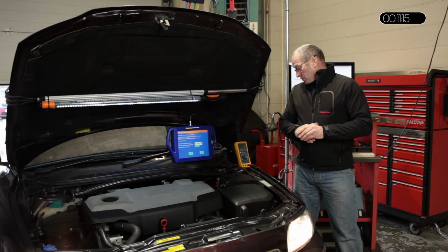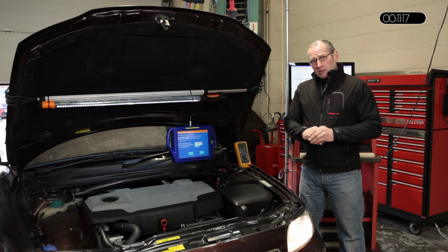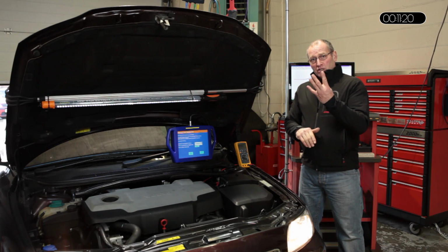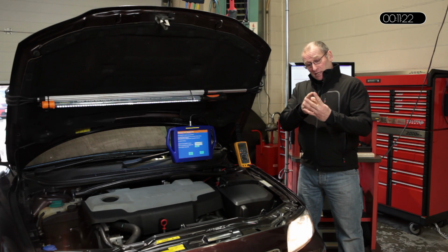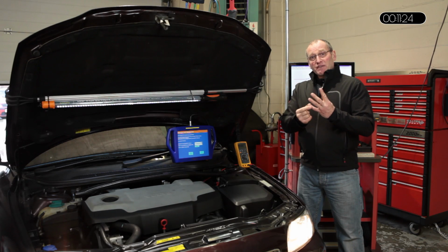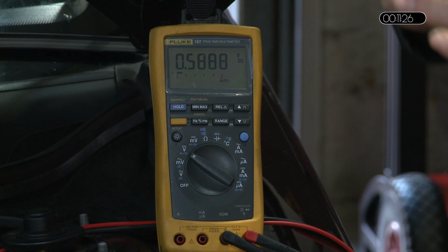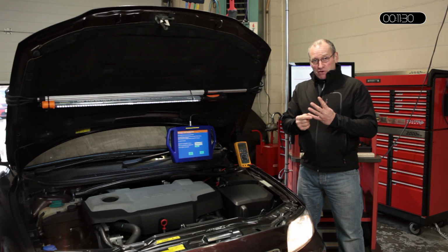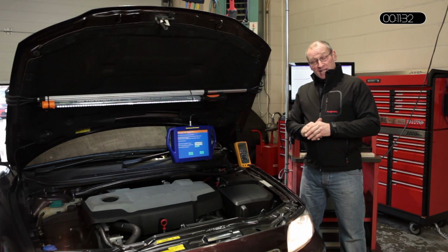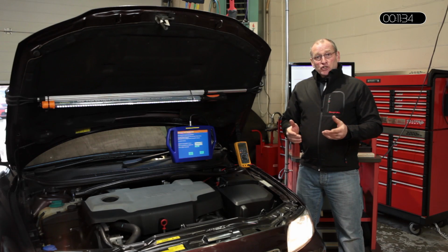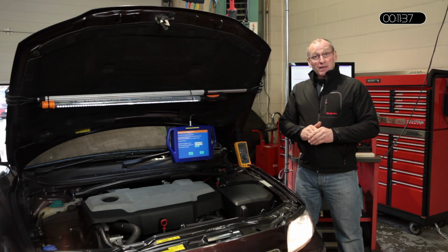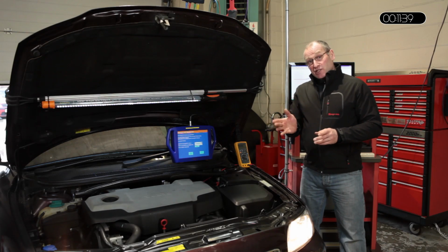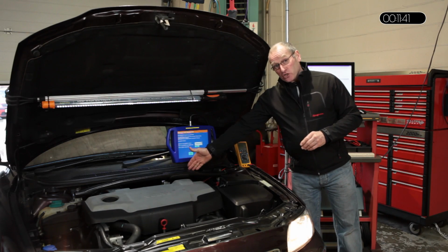Moving on to voltage. I mentioned earlier on the 4 key functions of any sensor: output, power, ground and environment. Before you blame an output error, ensure power, ground and the environment is correct. The environment in our case is soot. 2 hoses connect the DPF to the sensor. The sensor is slightly out of view at the rear of the engine on this model.